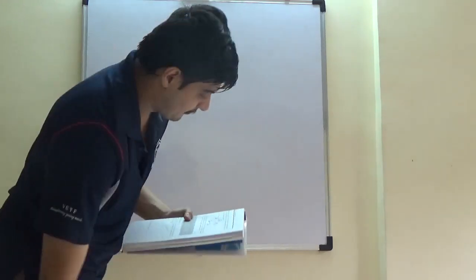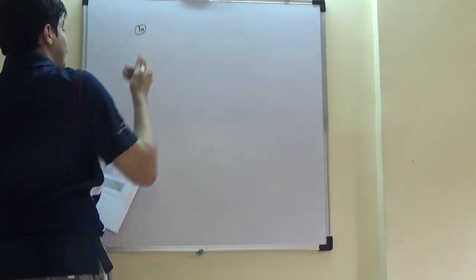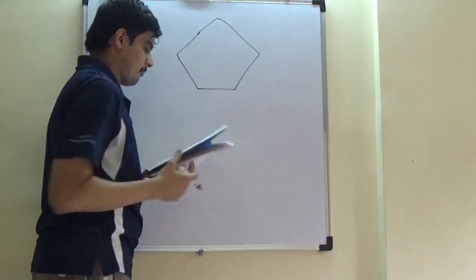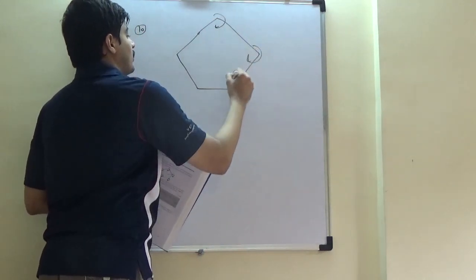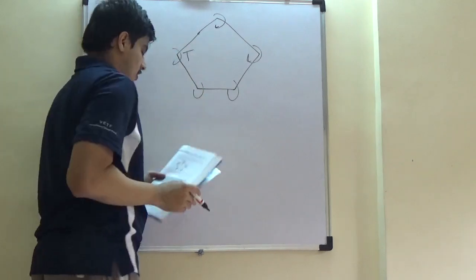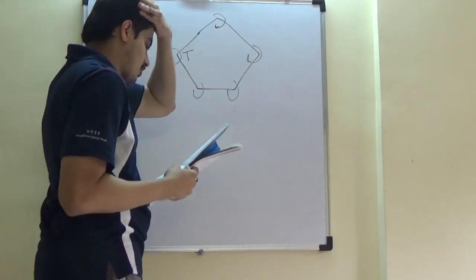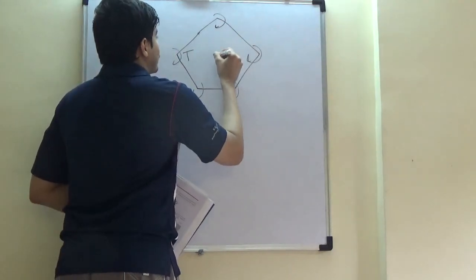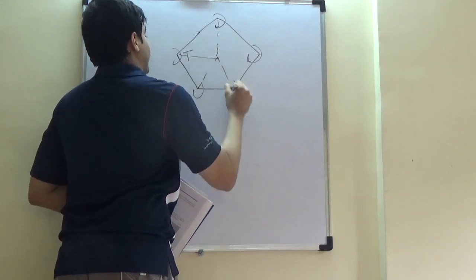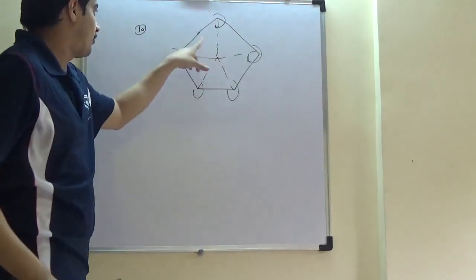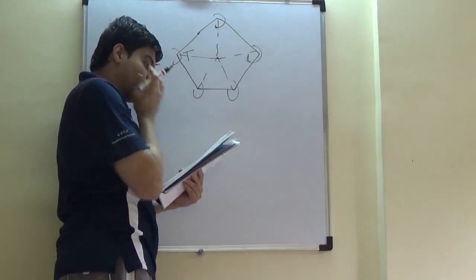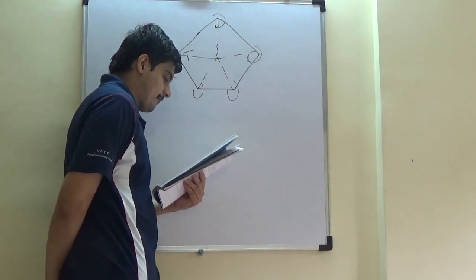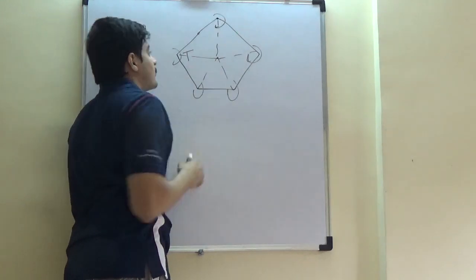Alright, this question is good. Simple but yet involved. We have been given a pentagon. Bear with me for my drawing, but it is a symmetric pentagon where on each corner a circulation in the clockwise direction, a vortex of tau, is placed. What is the pentagon made up of? These 5 equal triangles. We have been asked the tangential velocity component induced at any corner by the other 4 vortices.